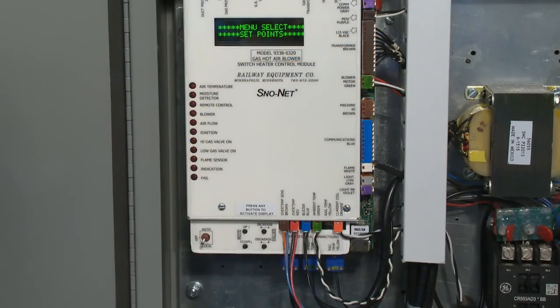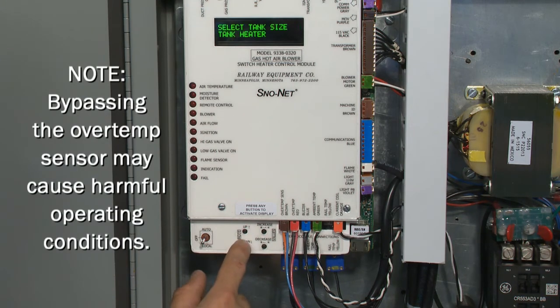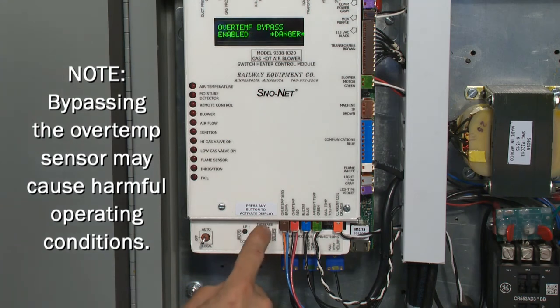To bypass the overtemp sensor, display Menu Select Set Points. Select Advanced. Enter the password 10. Then scroll through until Overtemp Bypass is displayed. Use the Increase or Decrease button to change to Enabled.